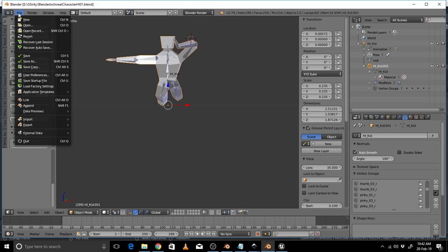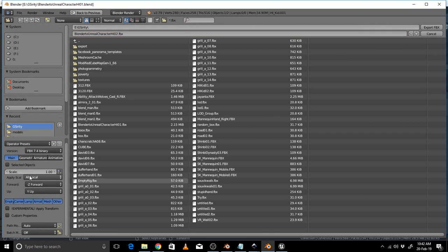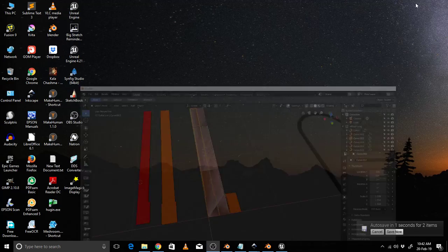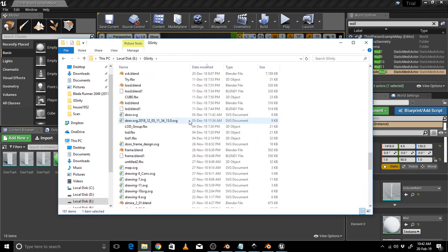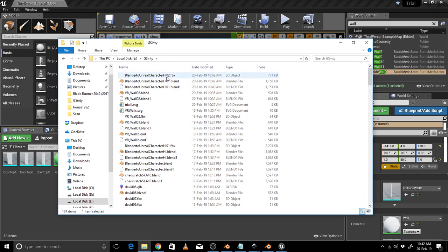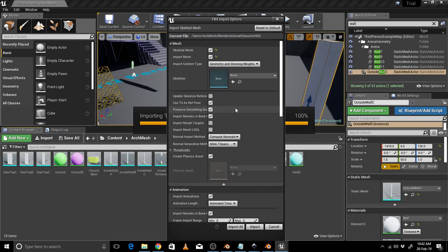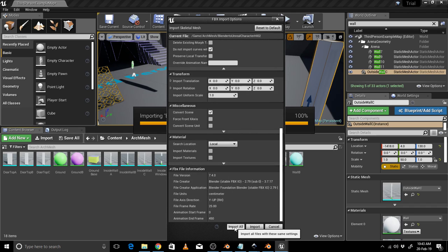This will do. And now we will export, and there are some rules while exporting FBX. We will hit plus one, and in our armature we have to stop this thing, and we have to make this root. This done, we can hit export, and this will be exported, and we can import our model here. So we have exported the model somewhere around here, and it will be at the top. Yes, here it is. So skeletal mesh, everything, let it be as it is. You just hit import all.